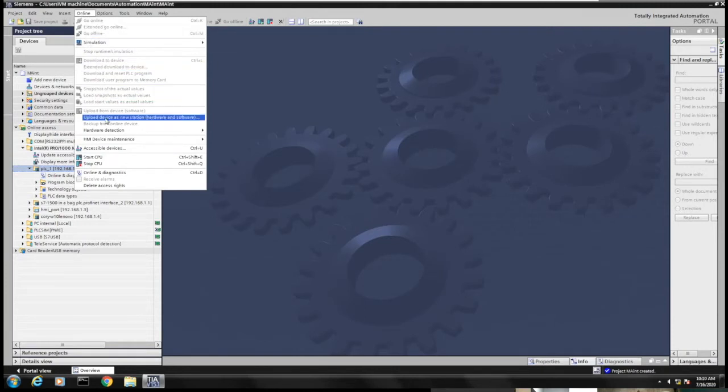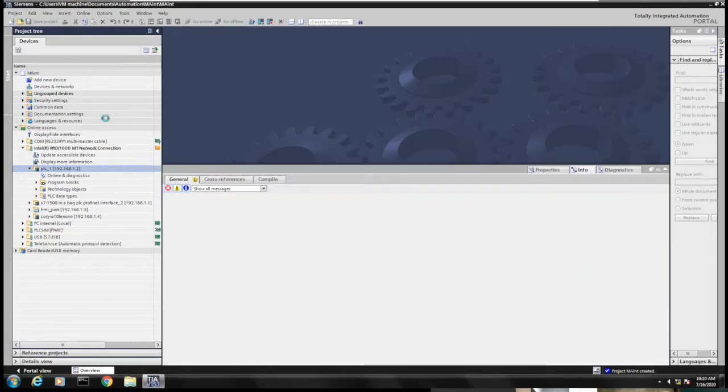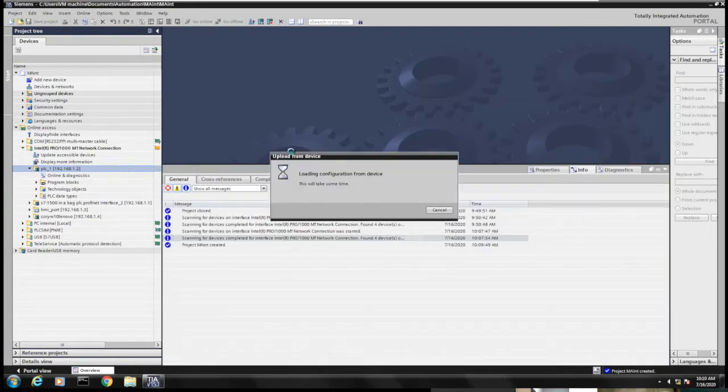So this is good for a situation where you don't have the original project, you just created a new project and you're on the network of your PLC, and you just want to upload the device, all of its local IO, all of its tags, all of its program blocks, etc. So we are going to start the upload. This may take a second.